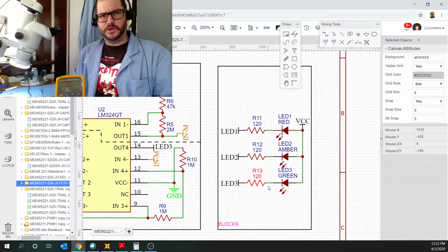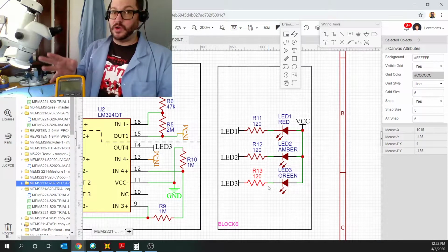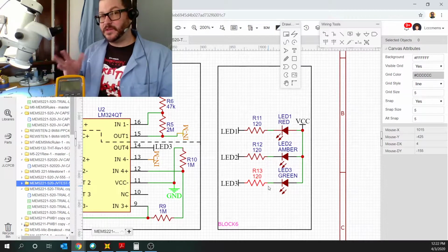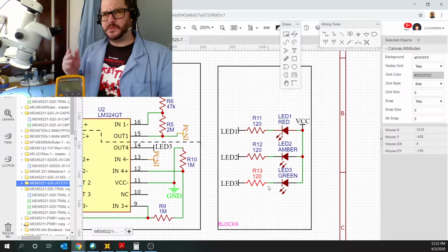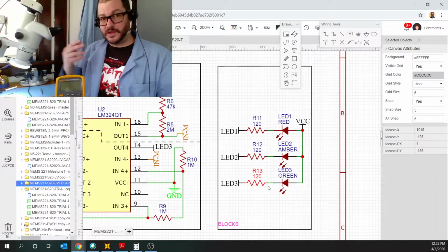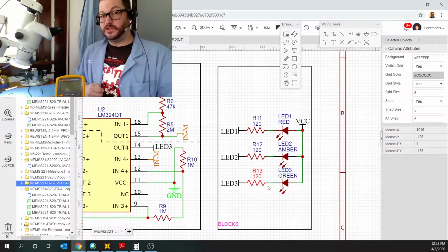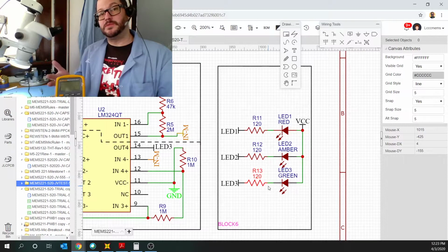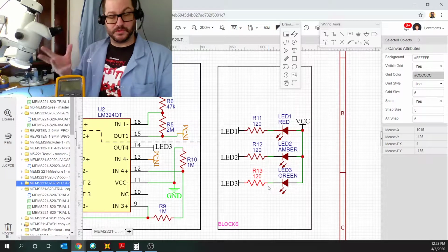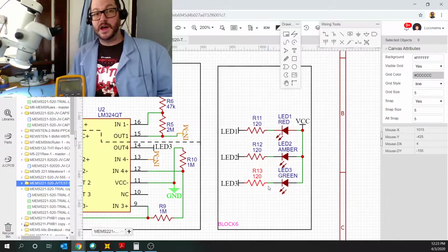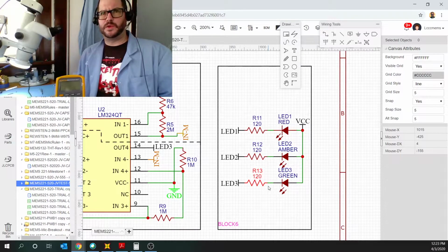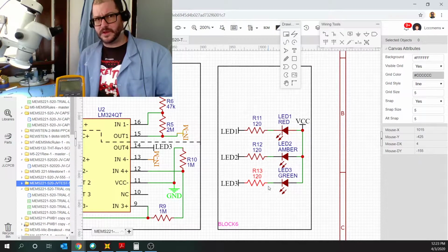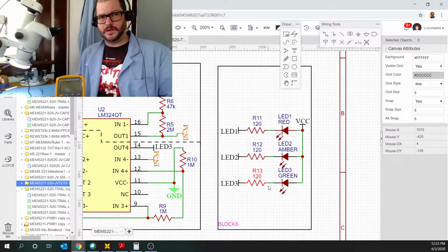They take a certain amount of voltage to be able to allow current to pass through. Depending on the LED that you're using, it will have different voltage values. Some LEDs, for instance, like red LEDs, can take as much as maybe 1.2 to 1.5 volts. They use that to allow current to go down and through it. Other LEDs, like blue LEDs, for instance, take larger amounts of voltage, anywhere between like 2.5 to 3.2 volts, to be able to turn on. And every LED is a little bit different. You want to look for what's called the forward bias voltage, as it's called in the technical definitions. The forward bias voltage is what the LED takes.